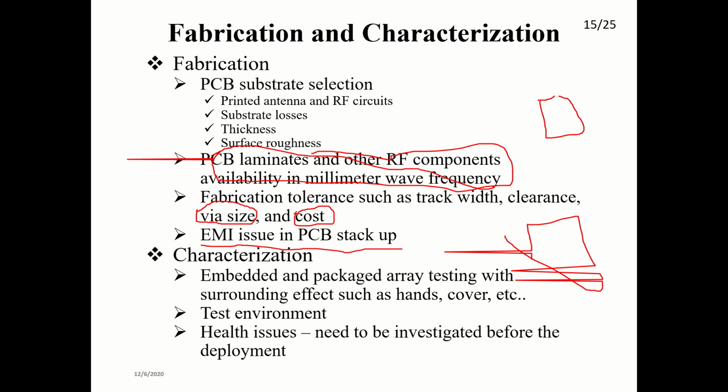So what was the problem? They went and investigated. Finally they found that this is the problem, because the antennas are on the side walls. When the person holds the hand there, obviously we are also made of dielectrics and water, and several contents are there. A dielectric will have finite conductivity, and we also have conductivity, so we may act as a ground. So we definitely affect the system, because we are also dielectric. Our dielectric will interact with the antenna characteristics. Antenna characteristics will vary when you touch it, and this effect will spoil the antenna's purpose.